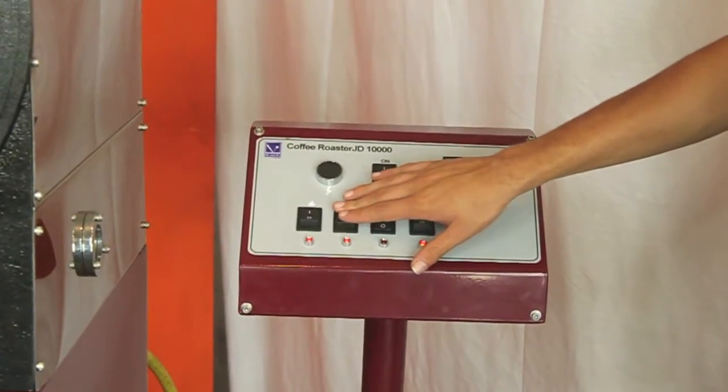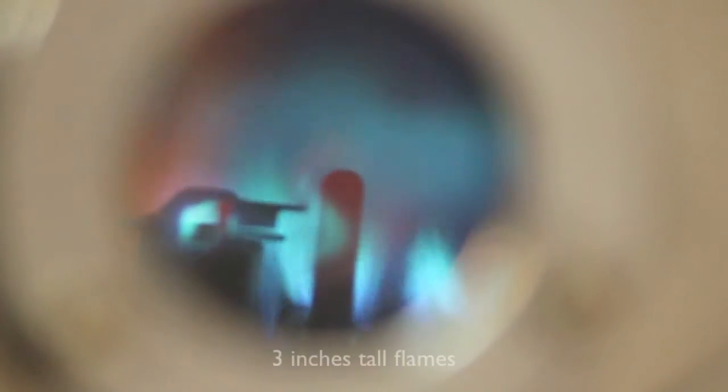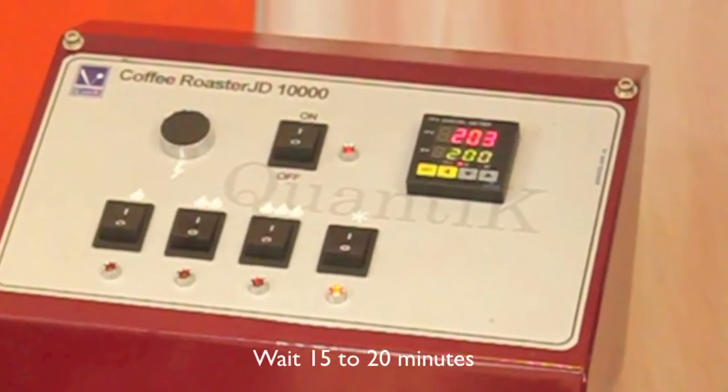Turn on the second and third heater flame intensity switches. Turn the regulatory and safety valve to the left in on position. Adjust the flame until it reaches 3 inches tall. Wait for the cylinder to be heated for about 15 to 20 minutes.